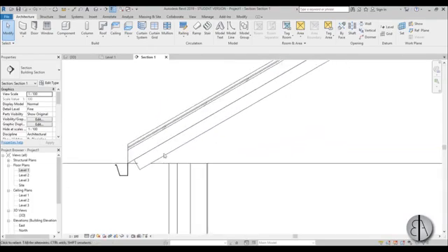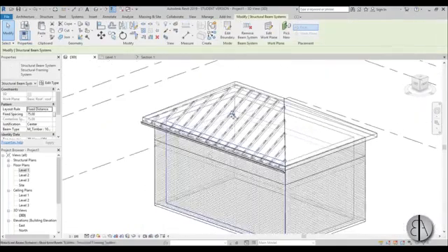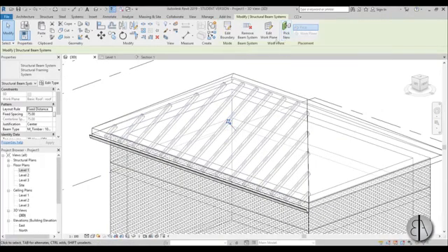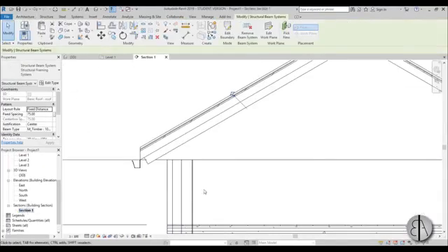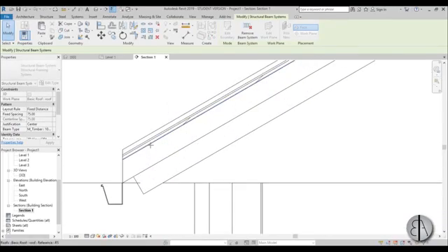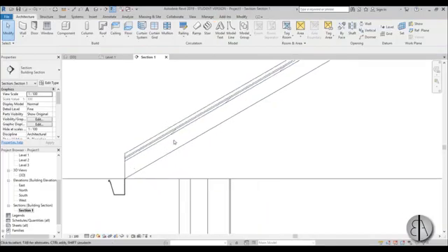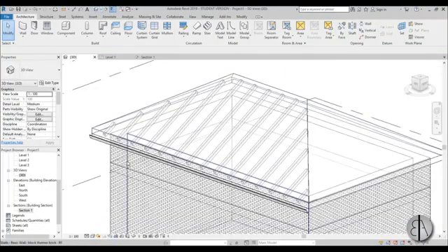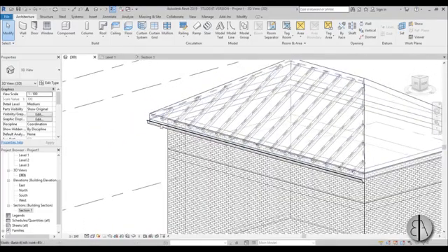material. So what we're going to do is I'm just going to go here in 3D, select this whole beam system, and again, if you don't know how to do this, don't worry, just go to the tutorial in the link below. So I'm just going to open this up, and now you just go here, edit work plane. To change the work plane, you go pick a plane, you go OK, and then you pick this plane over here. This is kind of the plywood layer, so these beams should be underneath over there. So now if I go in 3D, you can see they're kind of embedded in the roof. So that's the first part that was important to do.